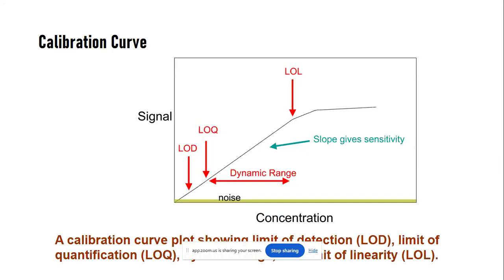So we need to understand the LOD. LOD is the limit of detection. Limit of detection means that obviously the instrument doesn't quantify the metal at 0.0001 ppb or ppm. So beyond a certain concentration, the instrument's accuracy starts to fall. For example, in the case of arsenic, ICP-OES doesn't provide precise results below 50 ppb, right? So below 50 ppb, ICP-OES does not provide precise results for arsenic.